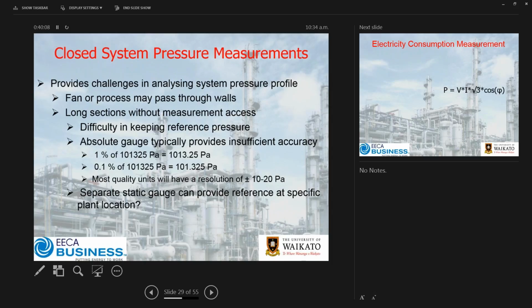to generate 20 pascals. And if you do the math in reverse, okay, if we take our density of 1.15, and then we divide by 9.81, 20 pascals is only 1.7, 1.8 meters. So effectively, for those of you on the old school numbers, every 6 feet of height is 20 pascals in pressure. That depends on the temperature that you're at, but notionally, 10 pascals is roughly, give or take, a meter. 20 pascals, nearly 2 meters in height.